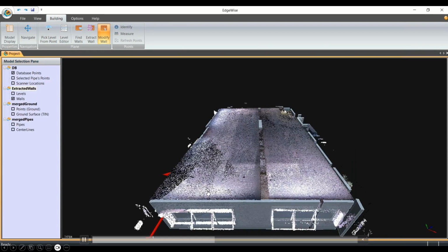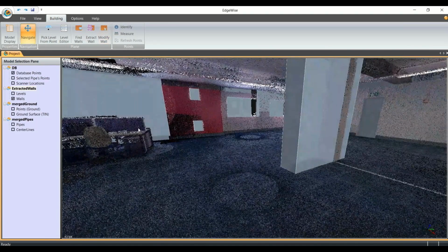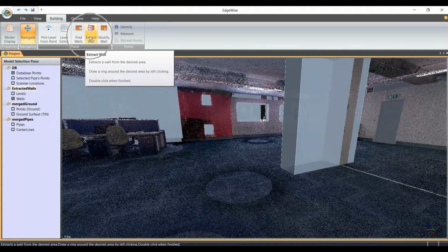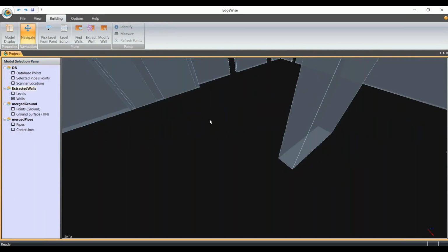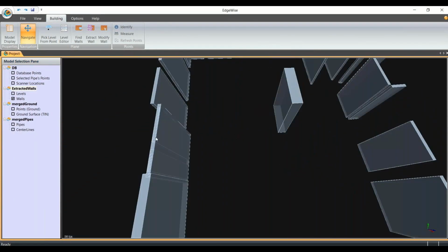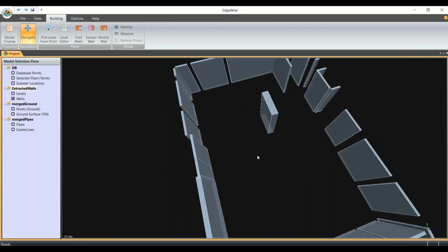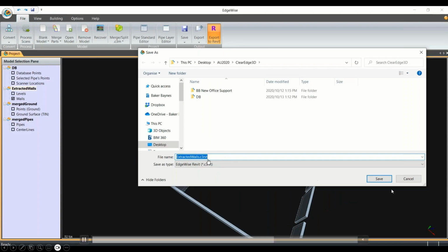Now, what happens to the portions that it actually has missed? So let's say this red wall, it didn't know what to do, or it didn't extract it correctly. I could go and define that area manually rather, and it will automatically extract it. So it will say, okay, this is actually a wall, and it is located at that portion. And after a few seconds, you can see it did extract it as a proper wall. And then, of course, I can go and adjust the alignment if it is slightly off, and so on. So you get the idea. It's quite easy to maneuver around here. So once I'm happy with this, I can then go and export it to Revit. You can see there's an export to Revit option on the top.